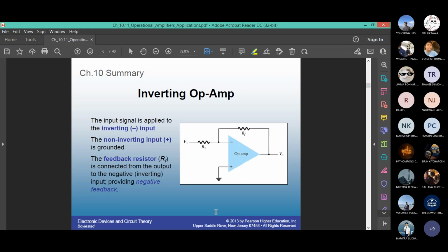I wouldn't say it's an equation. For example, in the case of JFET, we assume that gate current IG is 0 always. So what are the assumptions for op amp? The current going into the op amp is always 0. It means there is really no current.